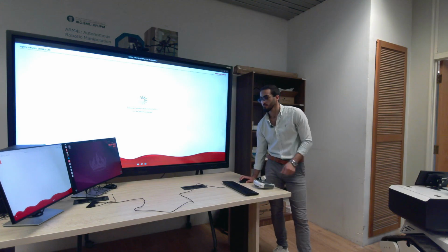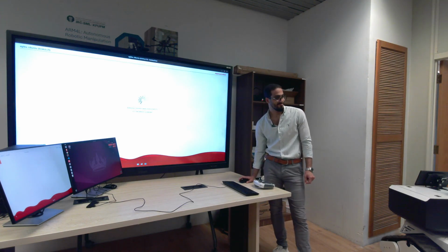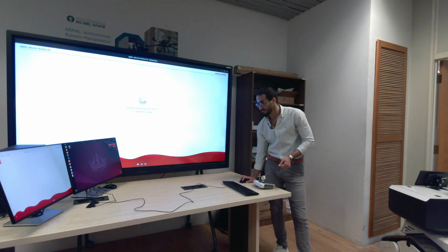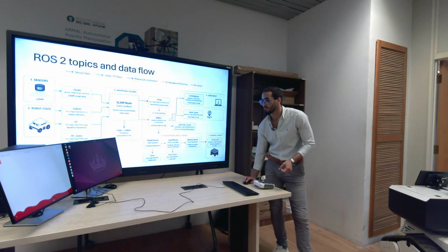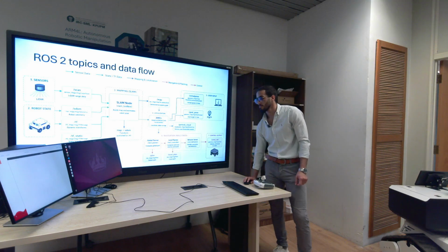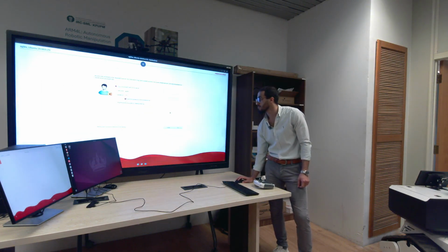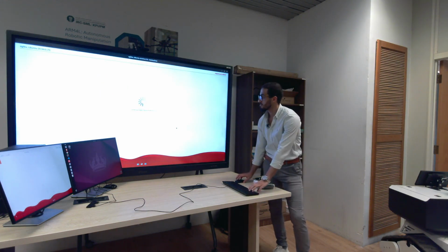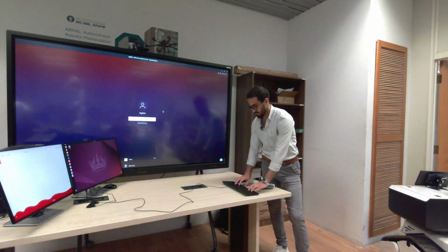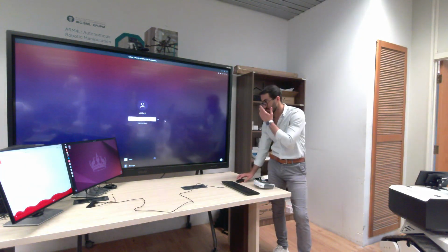How? I have to model the sensor. You have to build the EKF itself. All of what we discussed for many years. And that's the most difficult part. So you build the EKF, you build the state transition model and the measurement model, you identify all of the stuff, you tune the gains of the filter, and then you just let it run. And that's exactly the result. And then you go to the real robot and see whether it's satisfactory.